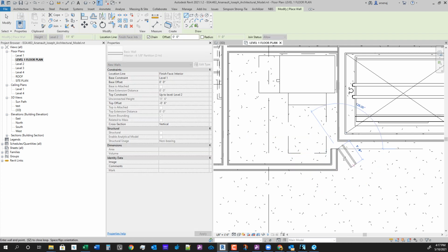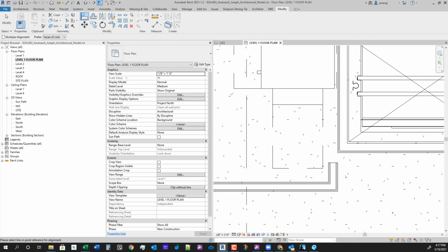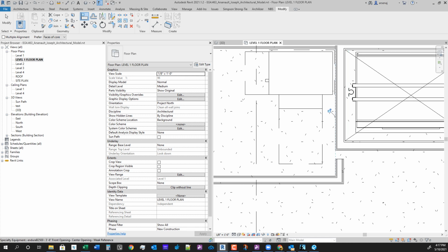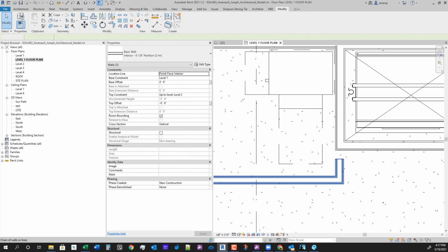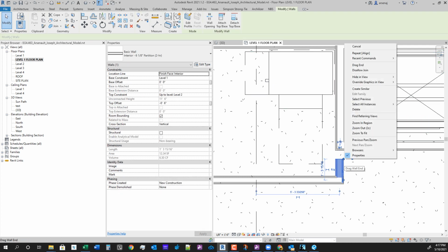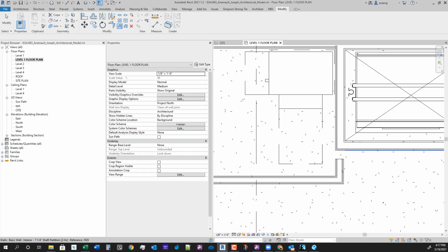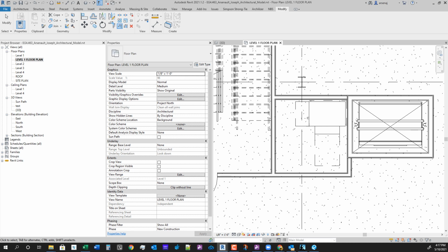I'm going to select this wall we drew before, right click on that as well, create similar, and then we'll create a little return wall here. I'm going to align the face of this wall with the face of the shaft wall. I'm going to pick this little end of wall here again, right click on that little round grip and disallow join, and trim to the face there.